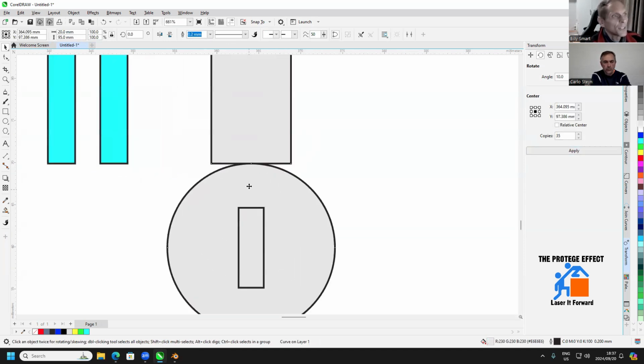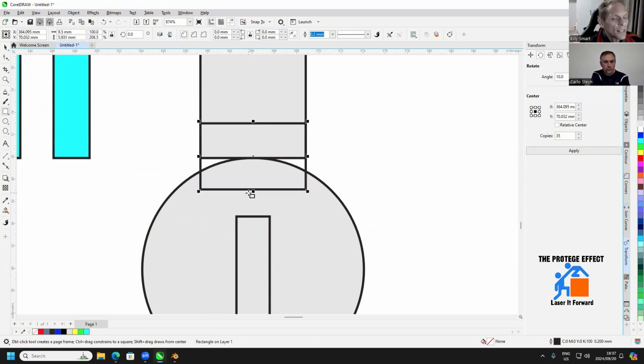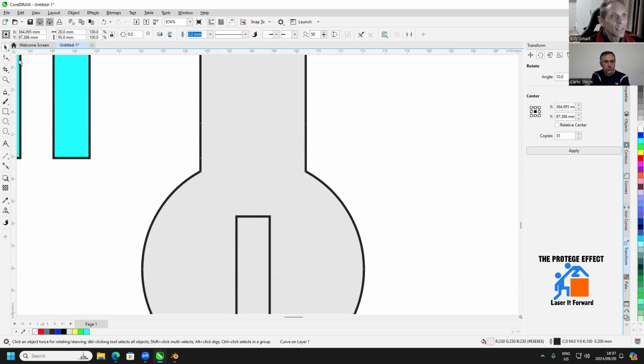And see, oh, no, if I put this in the laser cutter, it's going to cut that apart over there. Let me fix that real quick without using any fancy drawing tools. I just draw another block and weld it in. And if you're really OCD, you can go and clean up your nodes.